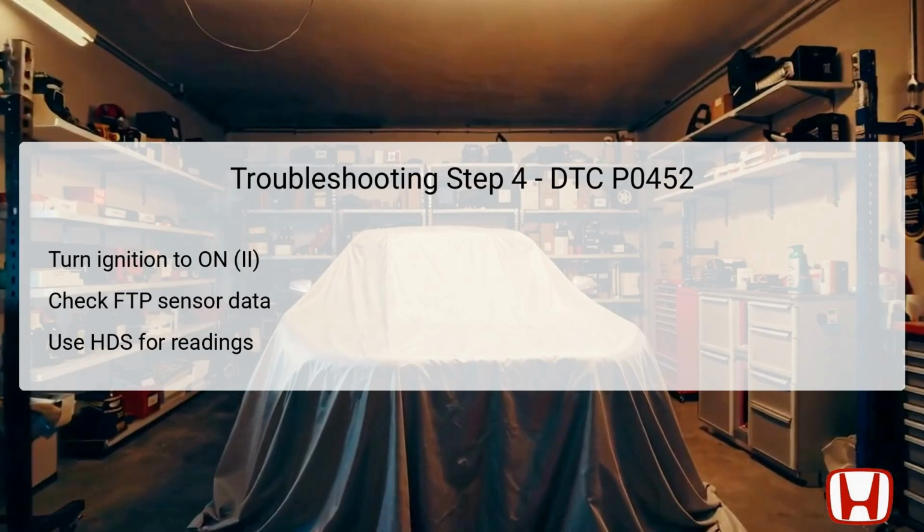These specific values are important benchmarks that indicate whether the fuel tank pressure sensor is operating correctly. If the reading meets these specifications, it implies that the sensor circuit may be functioning well. Conversely, if the readings are incorrect, further investigations into the wiring and connectivity would be necessary.